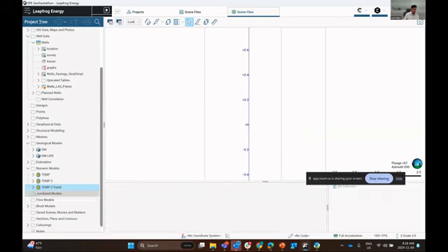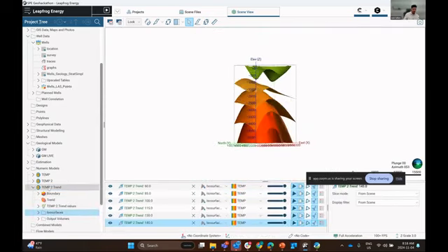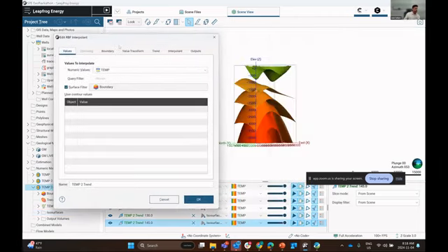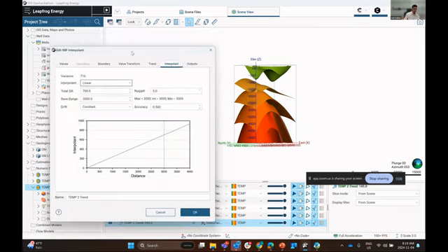So we can clear that scene and we'll look at the isosurfaces associated with this second temperature model. We can double click and there's a few things that we can change here, including applying a global trend, similar to how we can stretch our geologic contacts in a particular direction. We can also apply a trend to stretch this interpretation in a particular horizontal direction. We can also change the interpolant.